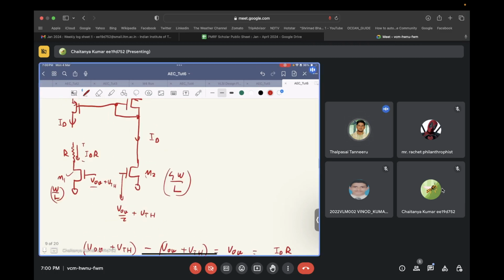Okay. So if this condition you need to satisfy in this circuit, what you will have to do is, let's say I connect the gate of transistor M2 to this and the gate of transistor M1 to this thing. Now the potential difference across this resistor, I have made sure that it is equal to the gate source voltage of transistor M1 minus the gate source voltage of transistor M2. And I push current of value ID into this.